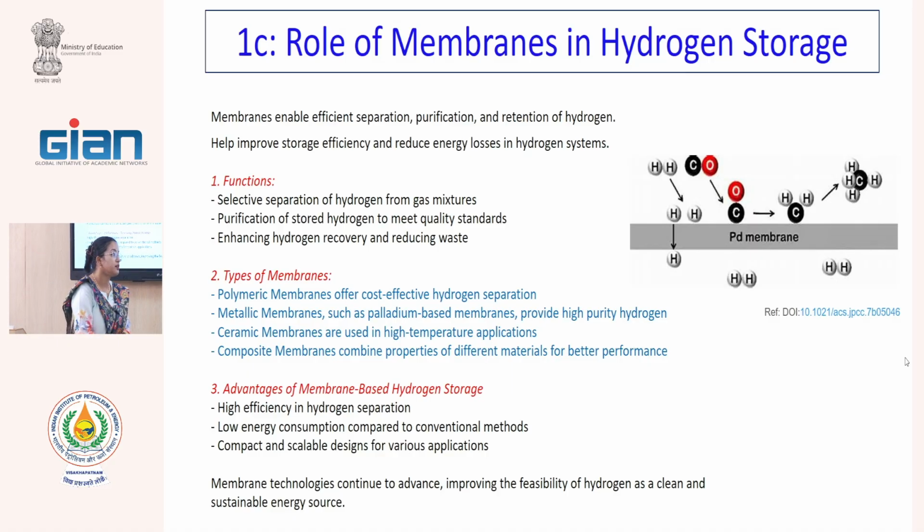In the previous lecture we were listening to various kinds of phase inversion and membrane preparation technologies. Sir was mentioning that when we are making gas separation membranes for this type of application, we do not expose it to the water or non-solvent. What we do is that we do evaporation of the solvent for this polymeric membrane, so that we can have a very dense structure of the membrane.